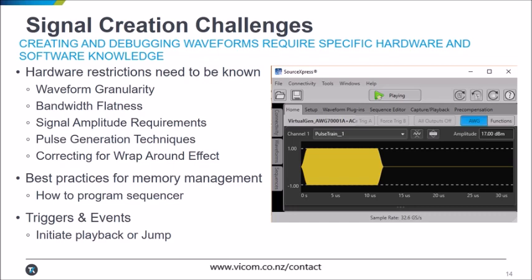So even with a granularity of, say, 12 to 48, the waveform has to be created such that the total waveform memory length is divisible by this number. If it isn't, then either the waveform has to be trimmed or duplicated so that it does meet these requirements.